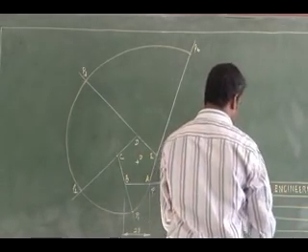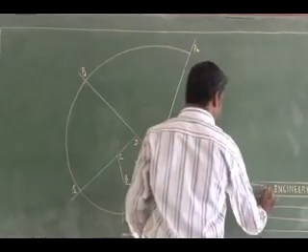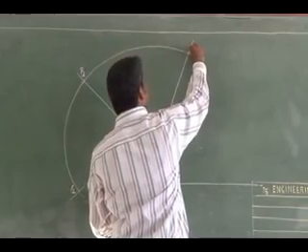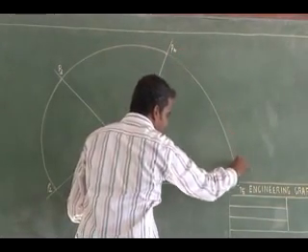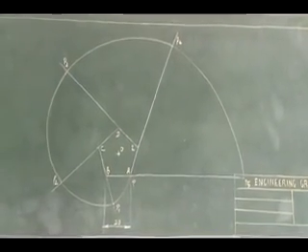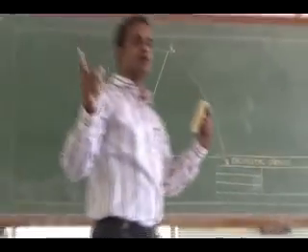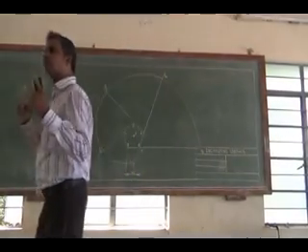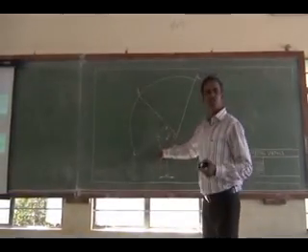Right, this is my P4, 35. So by currently drawing a curve, this is going to be my involute of a pentagon. You see here, these segments of involute should be drawn using your compass. Each segment will have a constant radius.